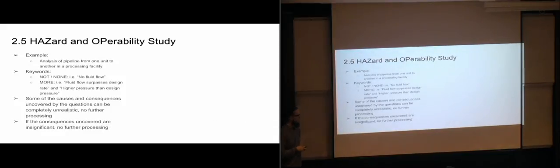And if some of the consequences that are uncovered by these questions are insignificant, we don't need to further process them either, such as using the more and less keywords on a lifting equipment. More load, that is very significant. We need to look more into more load, but less load, that's completely insignificant with regards to risk in this.